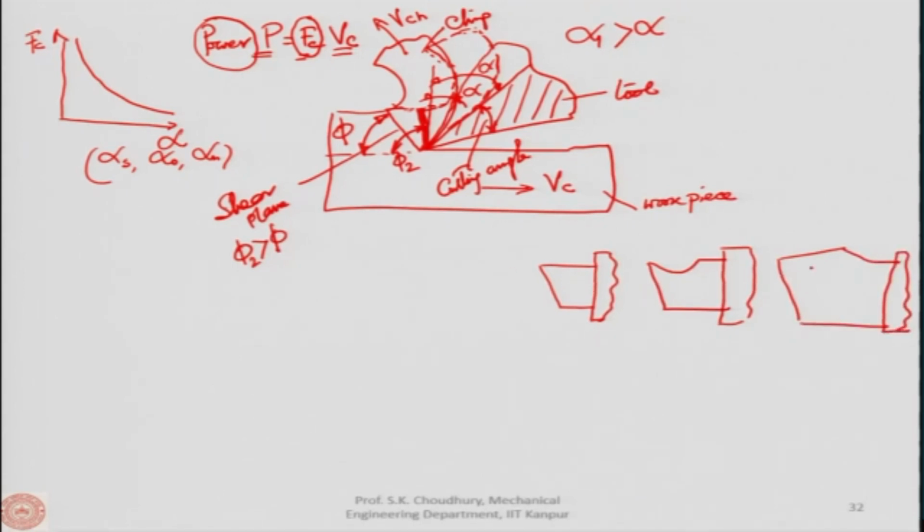all right. So, in all this I am just showing the rake angle, because you understand that in all this is the flank angle, okay, but this is the rake angle, all right. Here this is the rake angle, here this is the rake angle, okay. So, as you can see, the rake angle can be that alpha is equal to 0, here the alpha is positive. This is called the positive rake angle when it is in this way, and when it is in the opposite direction, this is the negative, okay, the negative rake angle.